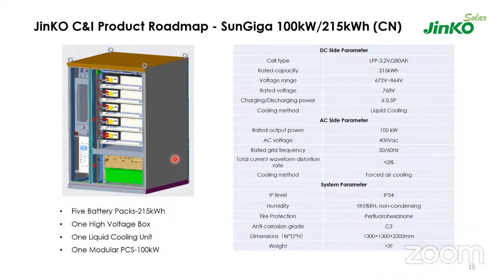And if you go for AC coupled systems, definitely you will have reduced round trip efficiency of the entire solution. But since we have certain regulations on DC coupled systems, people cannot go beyond 5 stacks within these DC coupled systems. Otherwise, we could even connect 5 gigawatt hours or 5 megawatt hours on DC coupled solutions, but safety wise, the compliance requirements cannot be fulfilled for higher capacity rating systems.